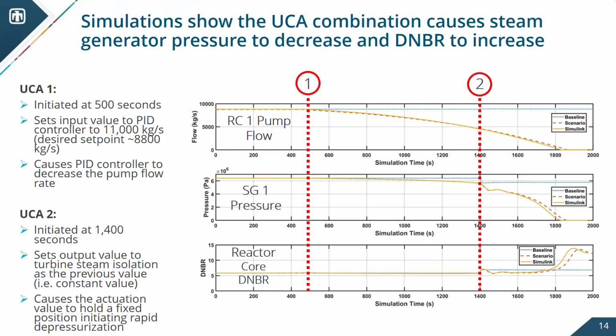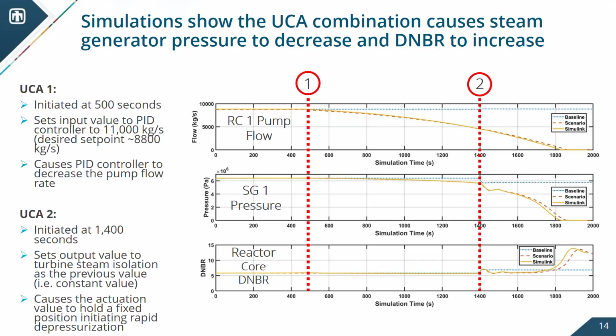And we were trying to say, you know, are there sort of resonant effects, right? Is there sort of a standoff timing where basically we create unstable states within the overall nuclear power plant that result in more significant impacts than we'd expect? And sure enough, we did. We created open source automatic tools, what's called manipulate process I/O, and we were able to essentially automate these tests and just stand off the timing between those UCAs. So in this example, that UCA1, which is that reactor coolant pump, we basically set the set point and we get the flow to 0.